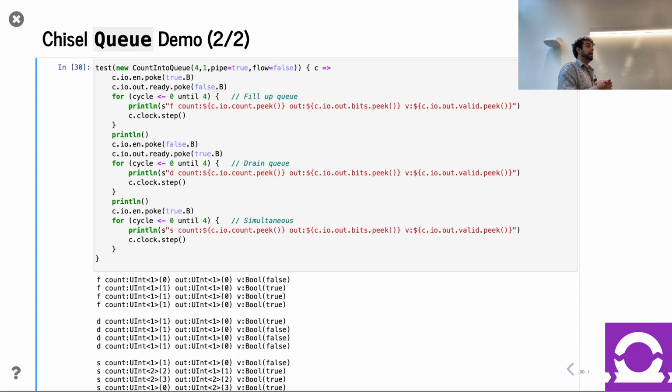It's a longer combinational path, right? Because if you go through the registers, the critical path is kind of whatever's in the producer to get to the queue, and then whatever is in the queue, and then whatever goes from the register to the consumer. If you have that combinational bypass path, essentially you now have a path that's through a portion of the producer, through the bypass path, and then through the consumer. So basically, you're now conjoining the producer's and consumer's critical paths, potentially. So it depends. It's not guaranteed to be a critical path. People use this. People do set this to true. But it's just to be aware of this, right?